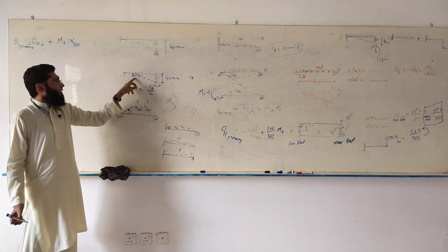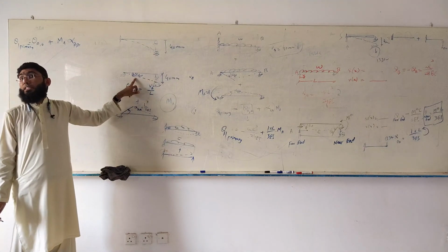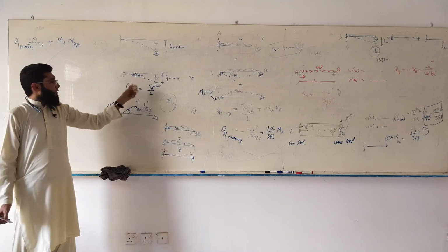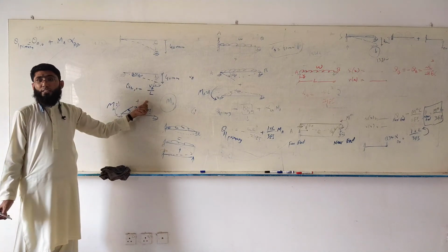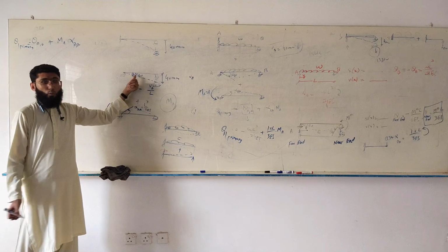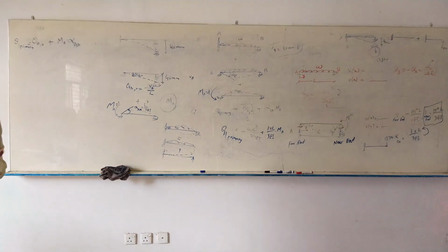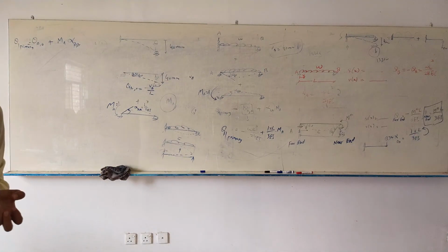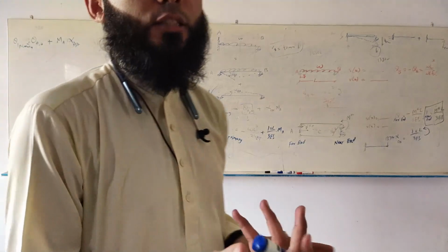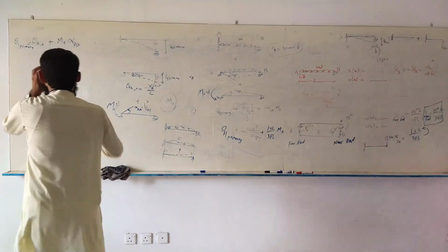What we're doing is calculating this displacement, because we have taken MA as our element. So this is going to be VB over L, the magnitude of the rotation at this end. The sign is clockwise, so negative. A rotation will be positive or negative based on whether it is clockwise or counterclockwise. I hope you can understand.